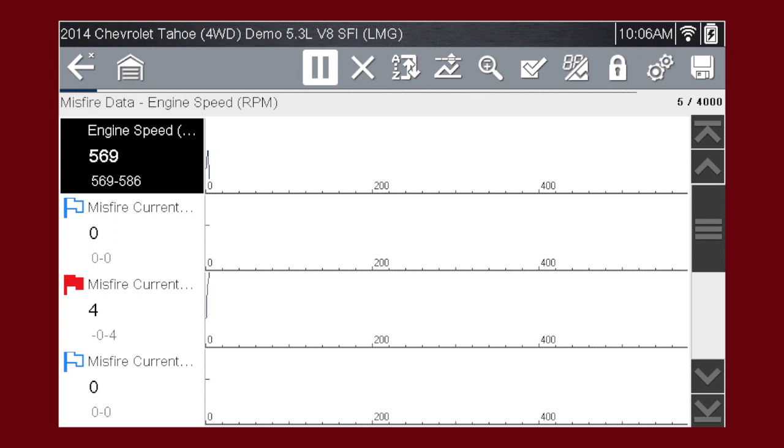In Smart Data, PIDs that display a flag have been preset and pre-armed. A blue outlined flag indicates the PID is armed and operating within its normal expected limits. In other words, the trigger has not been activated. When the flag turns red, the PID has exceeded the upper or lower limits. As the PID crosses the min-max value, the tool also captures a recording of the PIDs. Technicians use this movie to help determine cause, along with the next testing steps or corrective action.